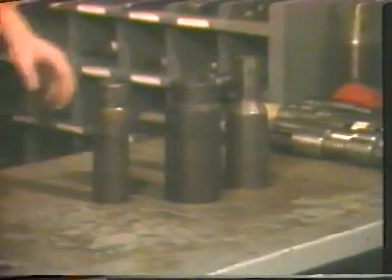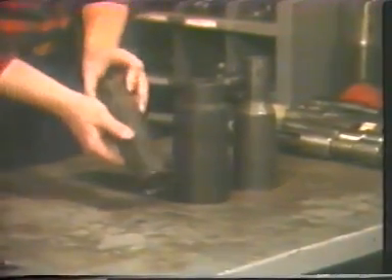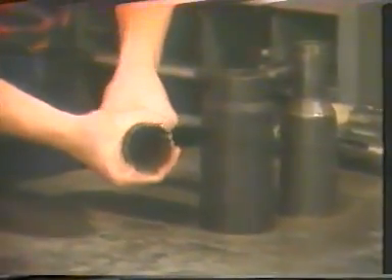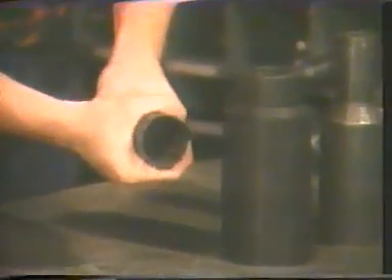Another type of wire finder uses a metal skirt, which is slotted to allow it to flex out against the tubing wall. The slotted cylinder will allow the wire finder to be run through reduced ID restrictions in the tubing and flex back out after passing the restriction. Once the wire line has been located and the upper end coiled or balled, the wire grab is used to latch and retrieve the wire line to the surface.